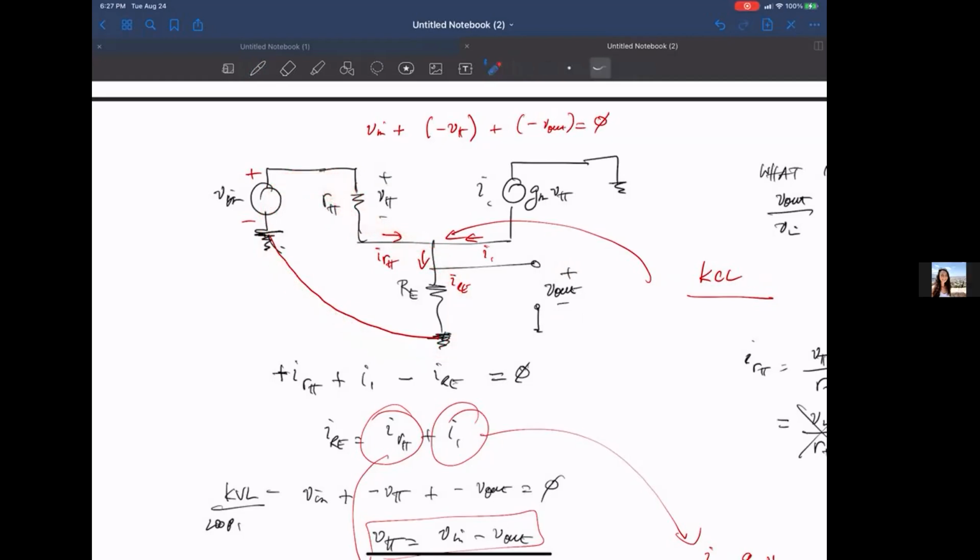I was just confused about the signs, but you explained that, so thank you. Another question: how did you get the directions of the currents? Was it for the voltage drops? You could go either way. This current is the direction of the arrow through a current source, which tells you what direction it goes. I usually define the current through a resistor as going from the positive to the negative node. So that's why I defined the directions that way.